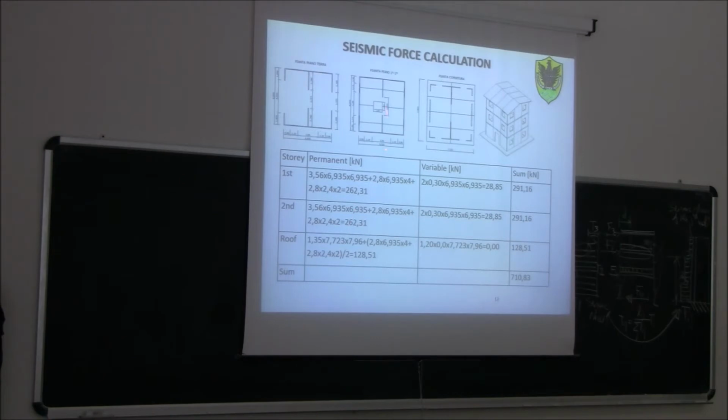But then a partition of this one. In our case, instead of partitions, they are all structural. Nothing changes if the wall is not structural. Usually you always use this kind of convention to assume half above and half below. It's an approximation.